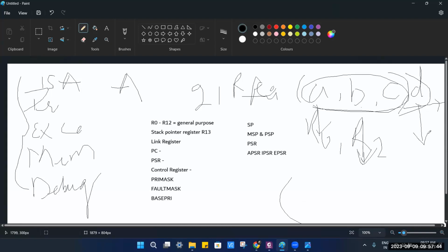Because they use, let us suppose, three registers for passing the parameters, if you use extra, that will go to the stack. And in embedded systems, we are most careful about the stack. It should not get a stack overflow. So while writing any real-time code, we make sure we are not sending more than three parameters. If we have to, then there is no choice.